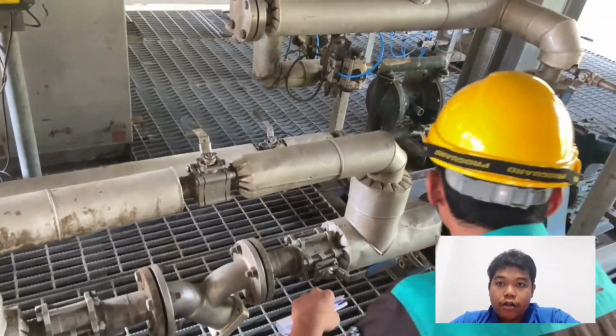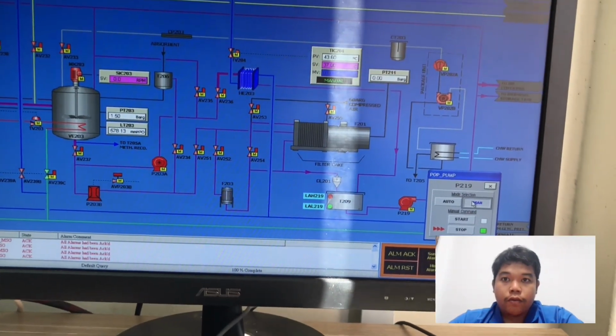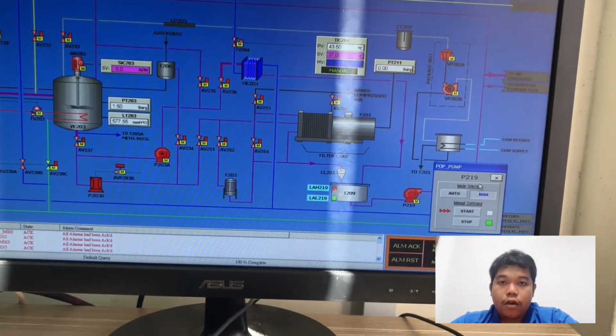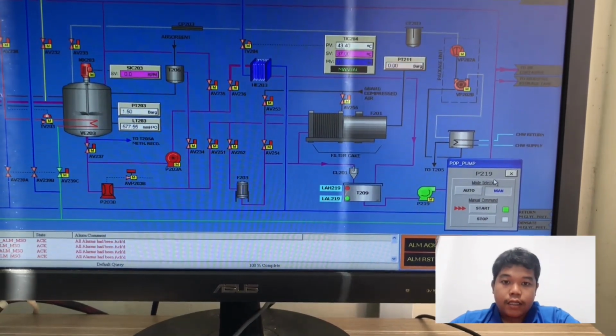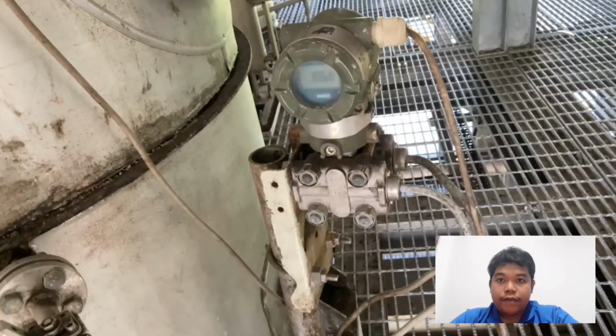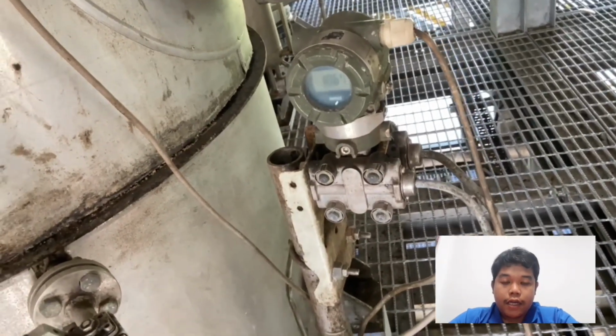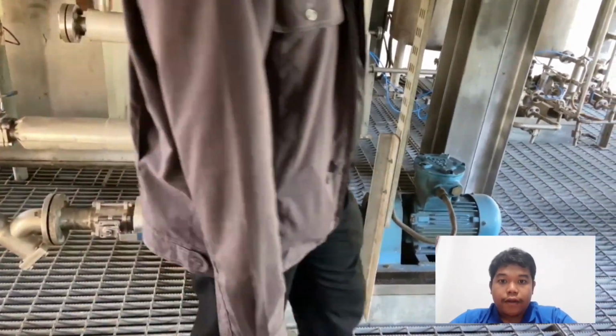Repeat the line tracking at the plant to release back the receiver from T209 back into vessel VE203. Open the valve on the pipeline and then switch on the pump P219 using the automatic method on the DCS and PLC until the green light to move the oil from the T209. Lastly, record again the oil level on the level sensor at the tank and the reading on the DCS and wait until the pump is automatically off.